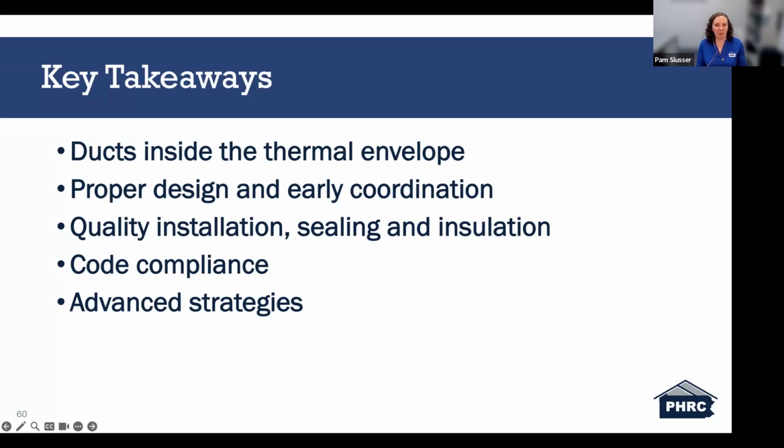And finally, advanced strategies like conditioned attics and compact systems make it practical to keep those ducts inside the envelope. When all of these come together, we get better performance, better comfort, and more durability within our homes. So that's why it's so important to bring those ducts inside the thermal envelope.